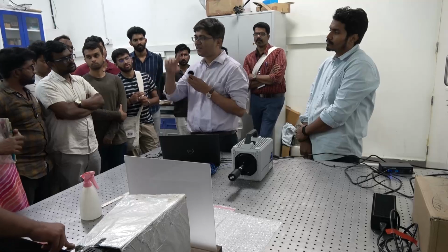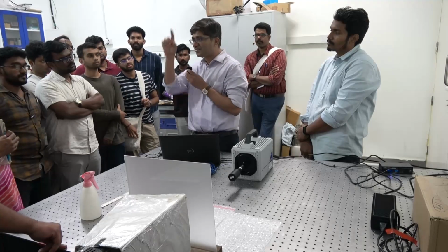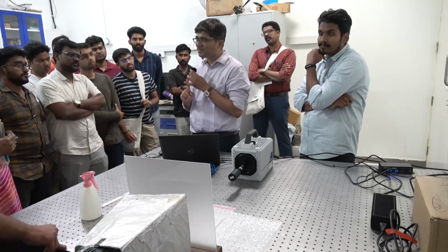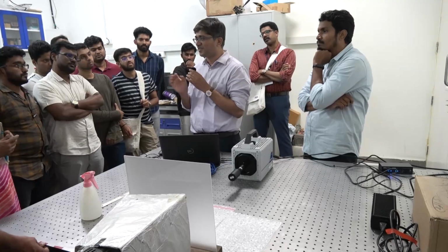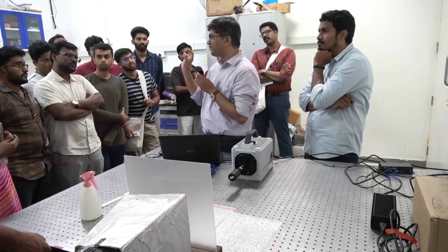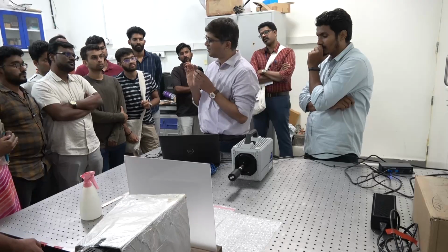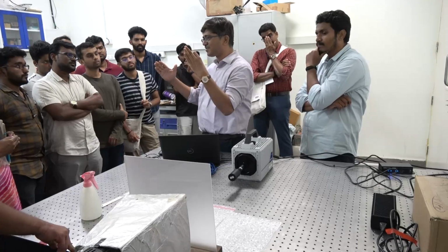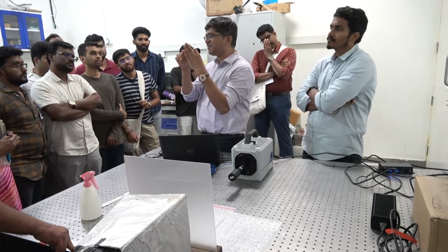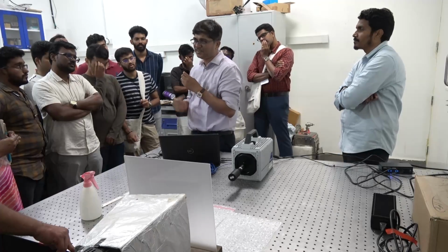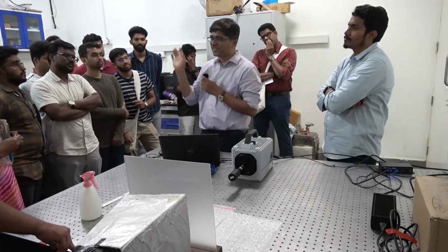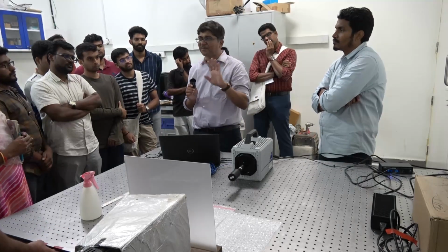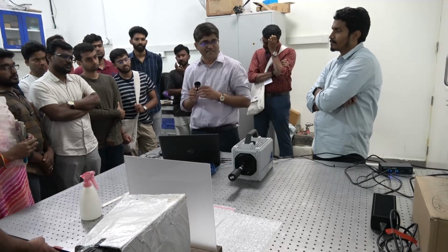You'll get sort of a velocity field, or size versus velocity. If you plot it, you get all scattered points, and same size drops at different places may have different velocity also. If I say a 100 micron drop in a spray, all the sprays will not have the same velocity. It depends on, if the spray is like this, over the edges they will have some velocity, at the center they have some velocity. So you will have it all scattered. It will not be a direct representation, otherwise you have to take a mean velocity, with all the statistics.